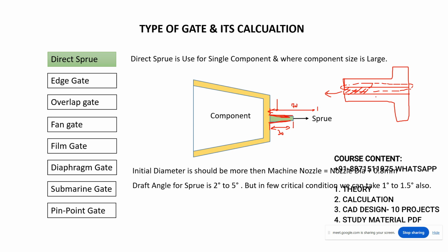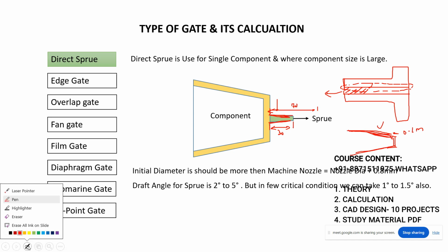But if you take the draft, it will go around 0.1 mm and it will detach because of the draft. That's why draft is very, very important.